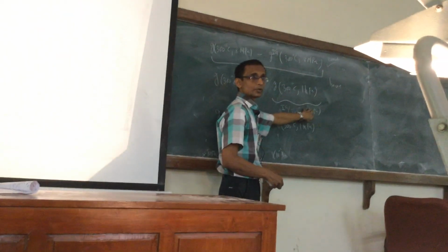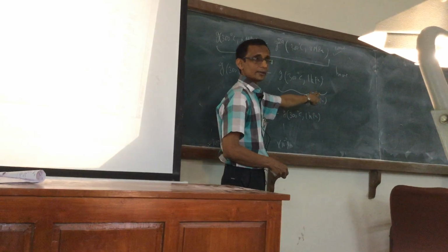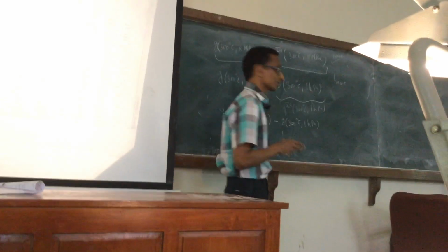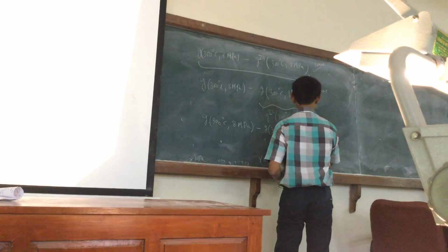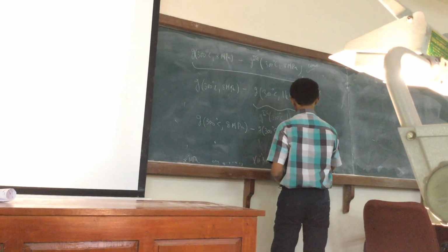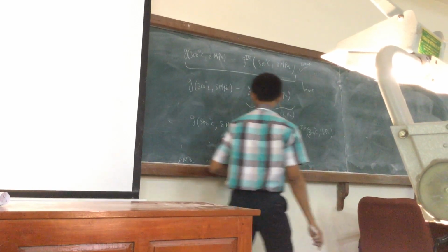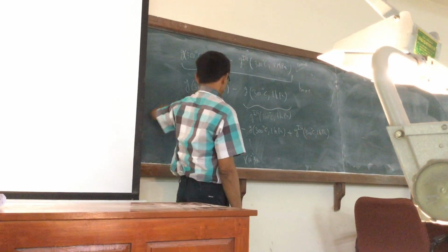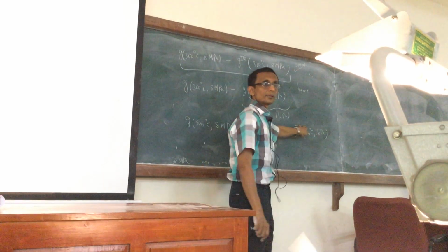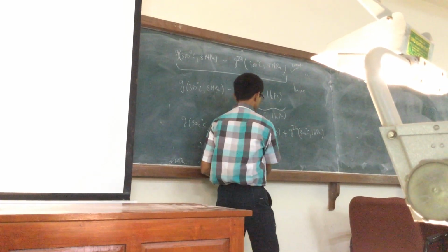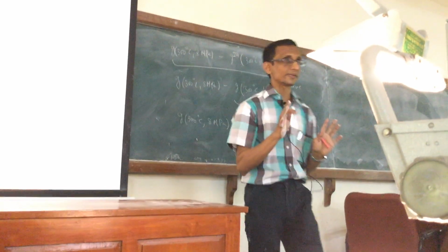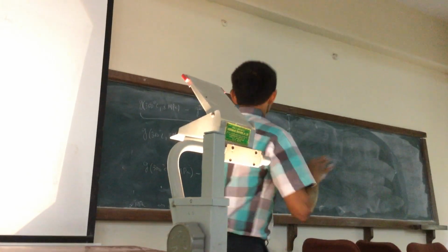Now I know that G at 300 degrees, 1 kilopascal is approximately equal to GIG at 300 degrees centigrade, 1 kilopascal. At the same pressures they are equal. So I write that plus this. I have written two terms, one negative, one positive. The two are approximately equal, so effectively I have added approximately 0. So it's not going to make any difference. But I am still left with this, so I have to subtract that.